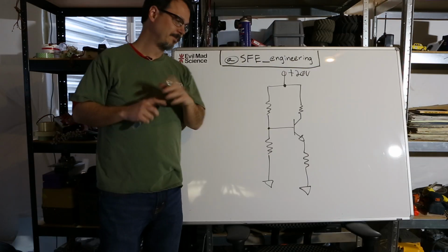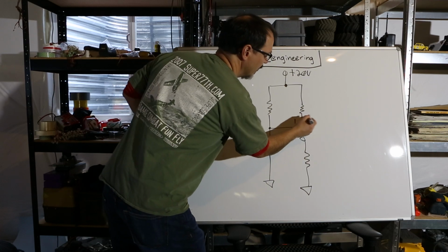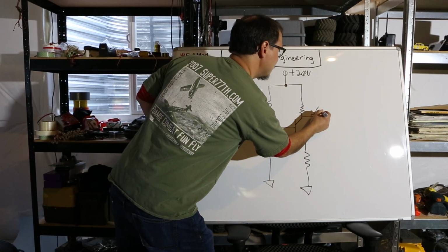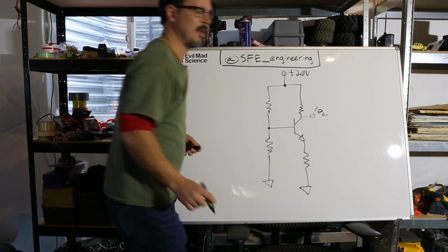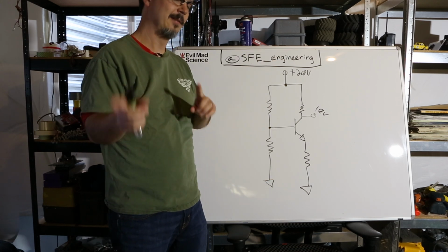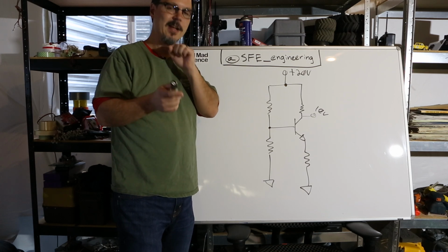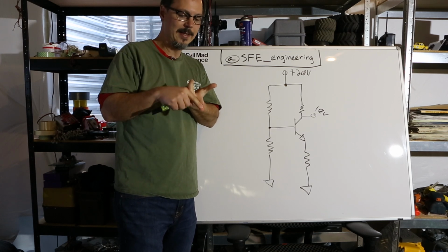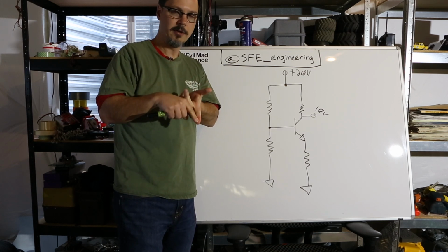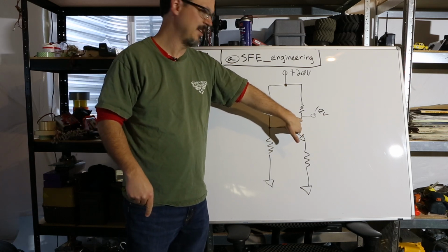Given the load line, we're going to try to set this up so that this point right here is sitting at 10 volts DC. That would give us a nice swing all the way up to 20 and all the way down to zero, ideally. That load line also had a current associated with it, didn't it? Yes, it did. So I need 10 milliamps of collector current and 10 volts, vaguely, of VCE.